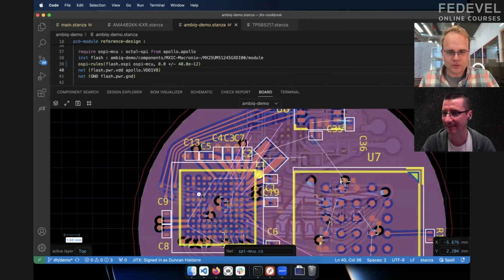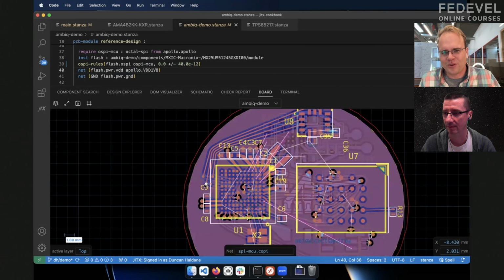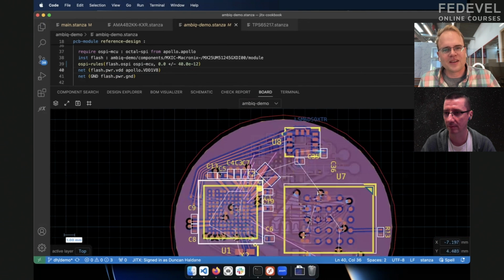So I think this sort of miniaturized, highly dense design, I think I can actually make it work on 4 layers. My reference planes are pretty good. You can't assume global constraints, right? You've got to work locally, but I think it can work.